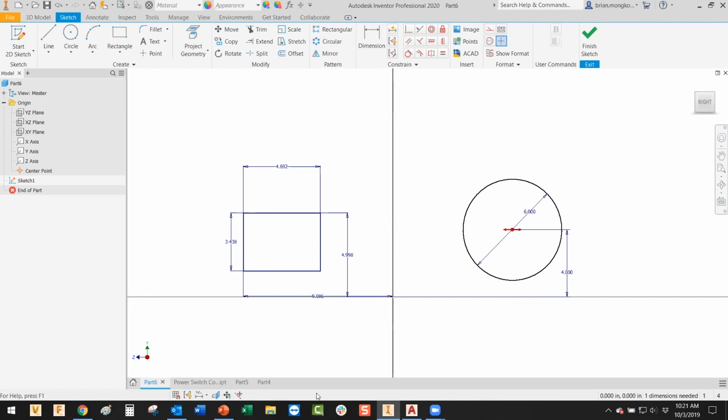Additionally, in the bottom right-hand side next to the total occurrences in your Inventor window, it'll tell you how many dimensions are needed to fully constrain or fully define everything. So Brian, just delete another one. Doesn't matter which one it is. That'll update the degrees of freedom, right? That arrow just became almost like a full-blown crosshair. And then it tells you there are 2 dimensions needed. So a combination of all of that will be able to tell you. Use both.